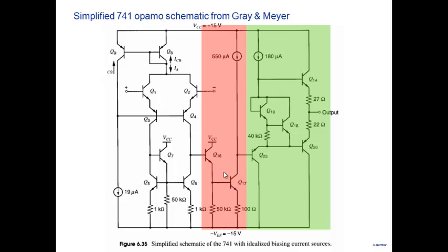Okay, and before this, what do I have? This transistor, as you can see here, is a common collector amplifier. The input to it comes from here. So it's a common collector amplifier and the output is taken here. So it's a common emitter stage which builds up a lot of gain and is driven by a common collector part. All right. So why have I put a common collector? Well, for impedance matching and all that, we'll see later on. So these two stages we should be a little bit more comfortable with now.